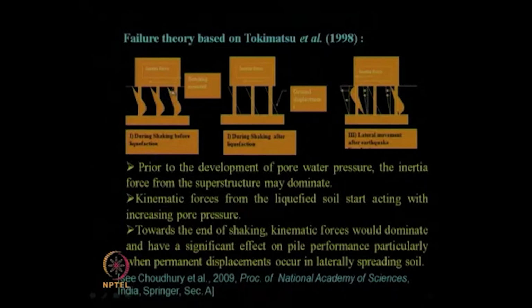Piles are subjected to extra bending moment because of the extra inertia forces due to the horizontal or inertia seismic load. In the next stage, stage 2, during shaking, after the soil gets liquefied, the ground will get displaced. So ground displacement occurs.